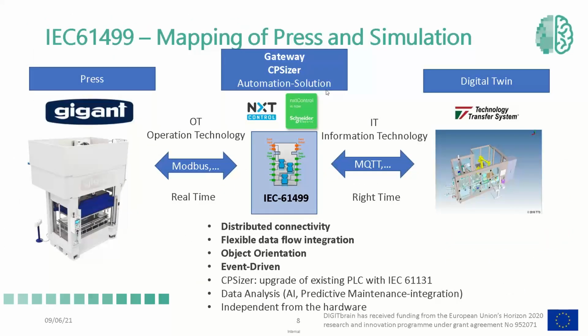So a little bit of explanation of how it worked, for people who are quite used to the shop floor. NXT Control created an interface with Modbus, but in that case, it's just because Modbus was a protocol which was already available in the factory. It can be interfaced with other protocols. And they convert to the IEC 61499 standard, which is a distributed connectivity standard. It's a very modern connection standard for machine tools.